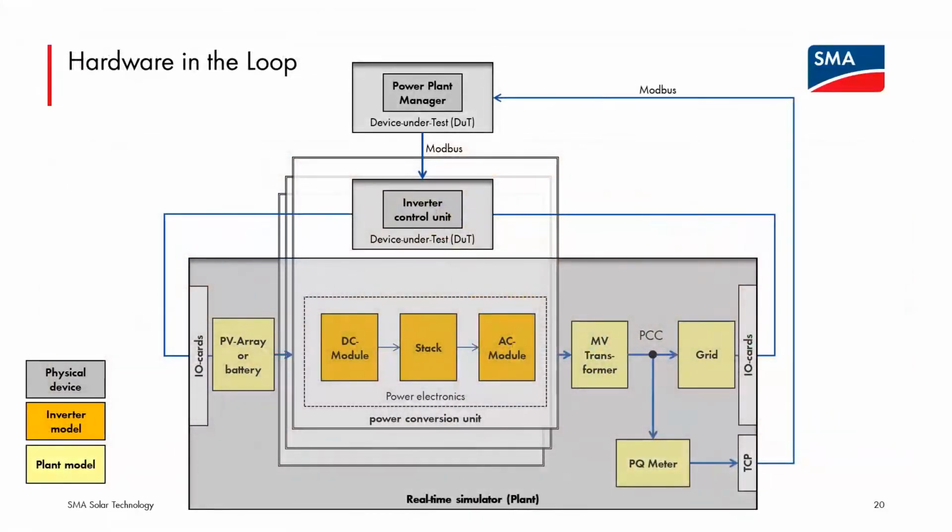So here again in the block diagram view, the powertrain of an inverter is modeled on a real-time simulator platform. Inverter and plant control units are real SMA equipment connected to I/O interfaces of the real-time simulator. That's a really excellent setup for us to do qualification tests or firmware validation, and even integration testing with customers' equipment, which is something we offer as an engineering service.